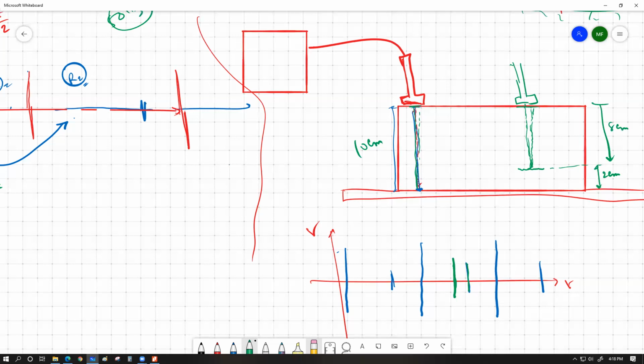The more length a wave travels through a medium, the more energy it loses to the medium particles. The less distance it has to travel through a physical medium, the less energy it loses. So if the reflection is received a bit earlier, we're going to have a bit larger amplitude, but this will definitely be smaller than the send pulse. You have to understand that the send pulse will always be the biggest because it's received almost immediately by the receiving unit in the probe. So that's what's going to happen.